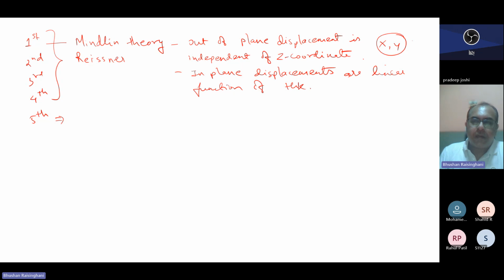So it is a perfectly bonded element, and then we are able to use it. If it is a composite slab, then it is not a perfectly bonded element, so we may not be able to use Mindlin-Reissner theory. I hope in these simple sentences, I am able to give you some hint of what the theory is going to be used for.